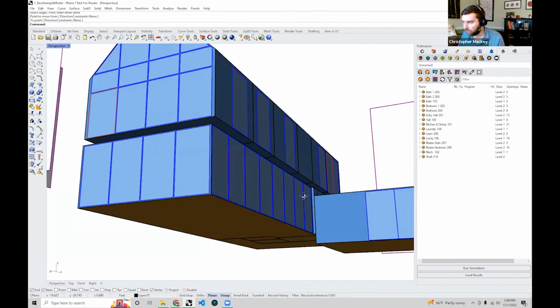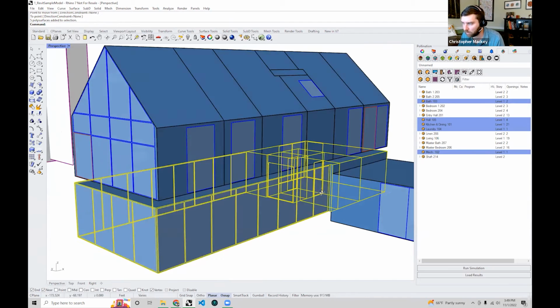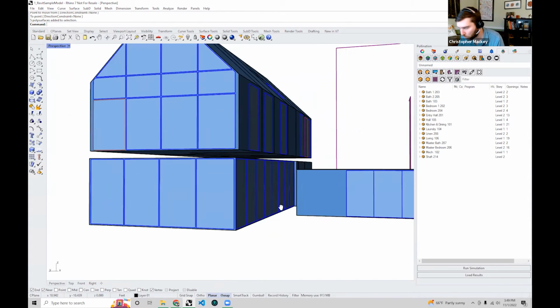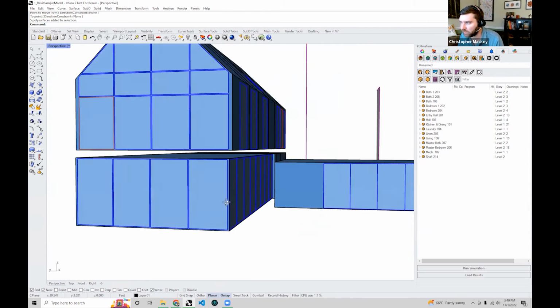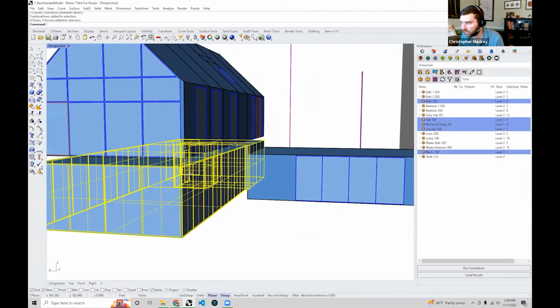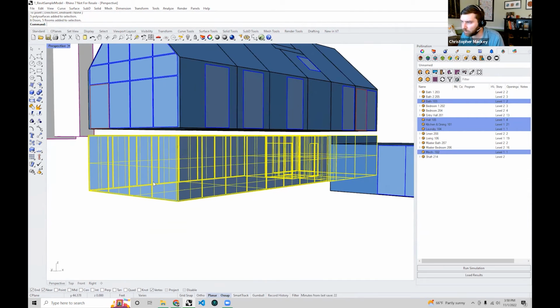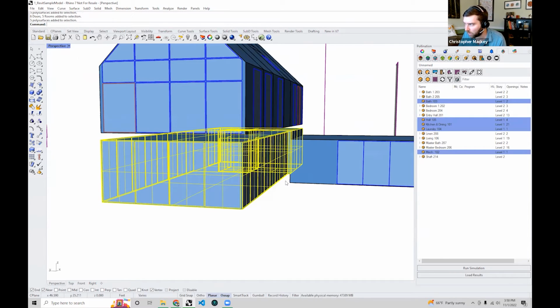But we still have to make sure that these geometries down here are touching the floors of the room above it, so that we can actually get the solve adjacency command to work in this case. So I'm going to do at least one more edit before I solve adjacencies. I'm going to make sure I have all these ground rooms selected. You can do this by dragging over just these rooms right here and getting most of them.